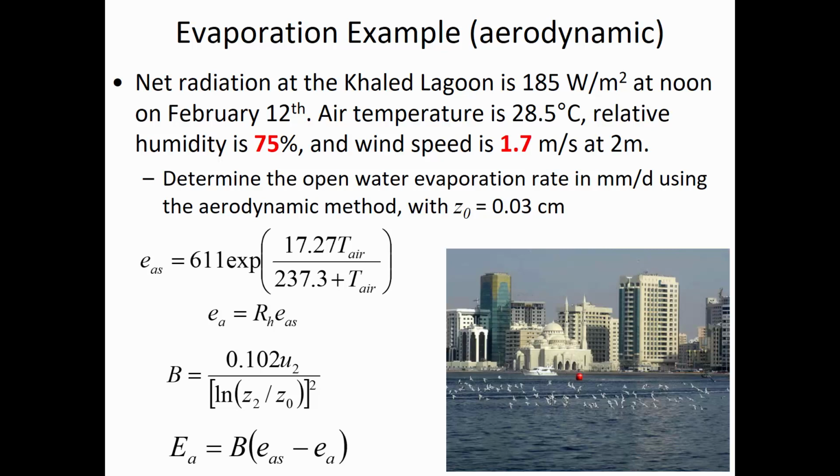So we're looking at how far apart is the amount of moisture that's in the air compared to how much can be in the air. So we'll multiply 0.002237 millimeters per day Pascal by the difference in the pressures.